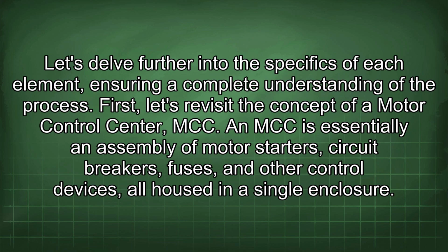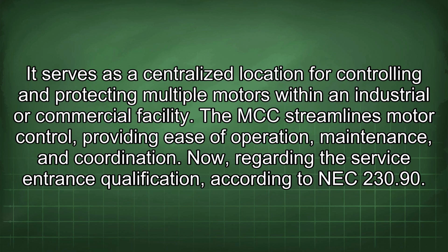Let's delve further into the specifics of each element, ensuring a complete understanding of the process. First, let's revisit the concept of a motor control center (MCC). An MCC is essentially an assembly of motor starters, circuit breakers, fuses, and other control devices, all housed in a single enclosure. It serves as a centralized location for controlling and protecting multiple motors within an industrial or commercial facility. The MCC streamlines motor control, providing ease of operation, maintenance, and coordination.